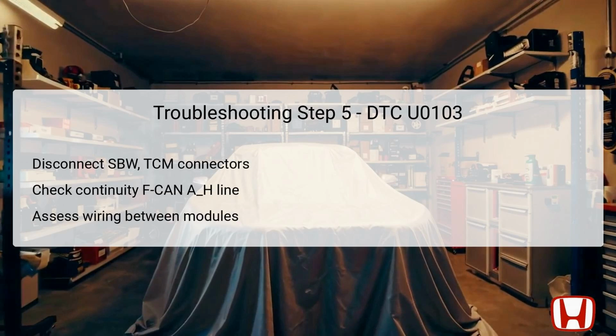In the fifth troubleshooting step, you'll check the FCAN-AH line for continuity to ensure proper communication between the SBW shifter control module and the TCM. Start by turning the vehicle to the off mode and disconnecting both the SBW and TCM connectors. Then, test continuity between the designated points, number 5 on the SBW connector and number 34 on the TCM connector.